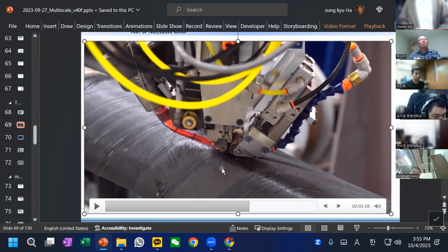Thermoplastic doesn't need a complicated chemical procedure. For thermoset, you need another factor: time. Time is a very critical component in thermoset. Why? Because we have to wait for the chemical bonding procedure. But for thermoplastic, all you need is just press and heat.